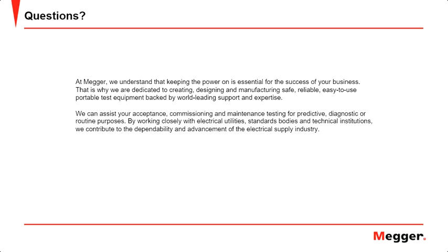VLF is not a destructive test. The VLF is made to expose whatever issues are already within that cable, whether it be from a termination, or dirt, or from the manufacturer.